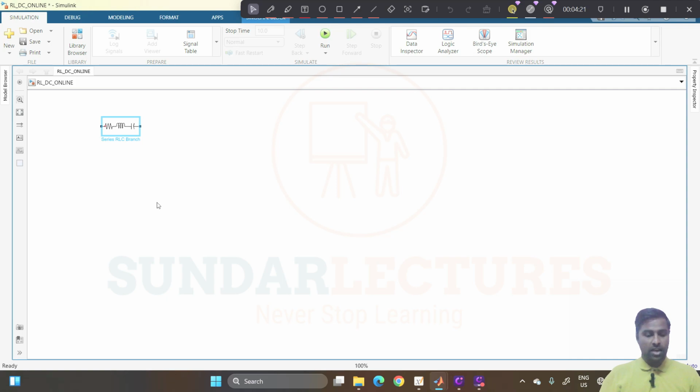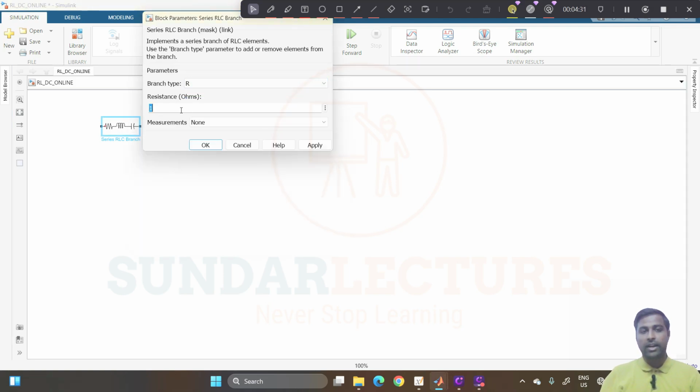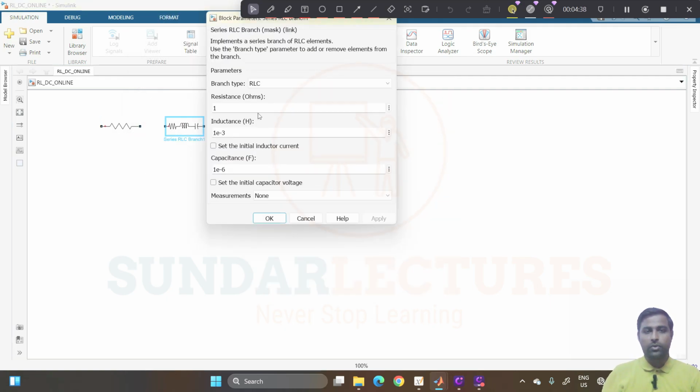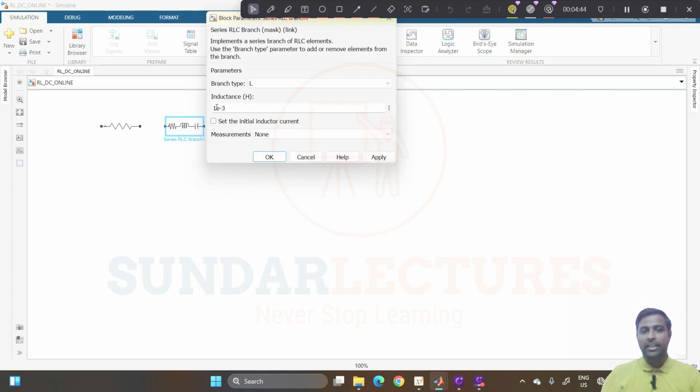So we need R as well as L here. I have taken it like this. Double click this one. You can see a branch type. Go there, get R, and give 100 ohms. Any value, no problem. Then you double click this branch, make the branch type L, and in L we are going to take 1 millihenry.